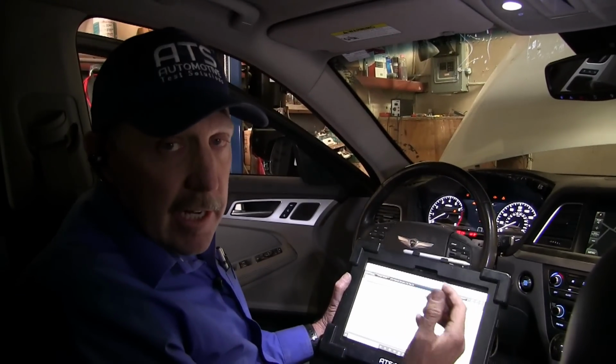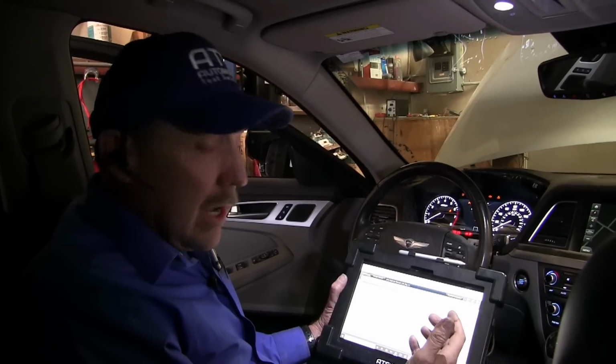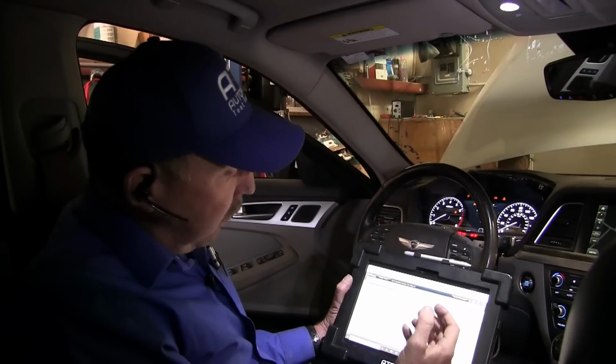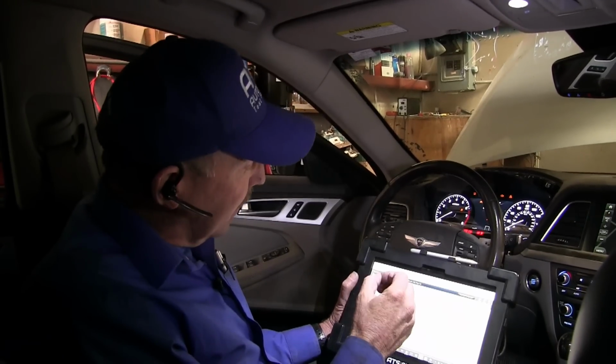What that means is, this is an engineering strategy. So if you're an engineer, one way would be to be directly on the bus like Ford would be. Ford's bus systems are wired directly from the DLC directly into the CAN bus, and they're hardwired. Now what that does is if I plug in a scan tool, it can disrupt the bus and I can set codes or have problems.